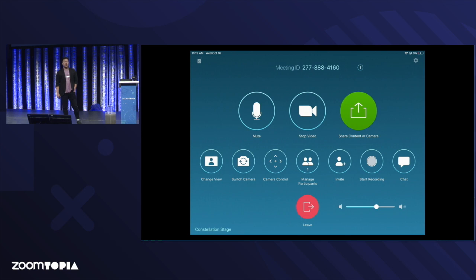It's USB cameras. It's not HDMI cameras. If you were doing HDMI, you would be bringing it in through a capture device. So if I was using, for example, the Magewell capture device, you could have even multiples of those, and in that list, it would show up as Magewell capture device instead of knowing what's attached on the other end of it. And then if you wanted to control that, you would program that into the native control. There's not a good way at the moment to do camera control of HDMI cameras that are captured outside of that. We do have the ability to use USB RS-232 devices for anything that speaks Visca.